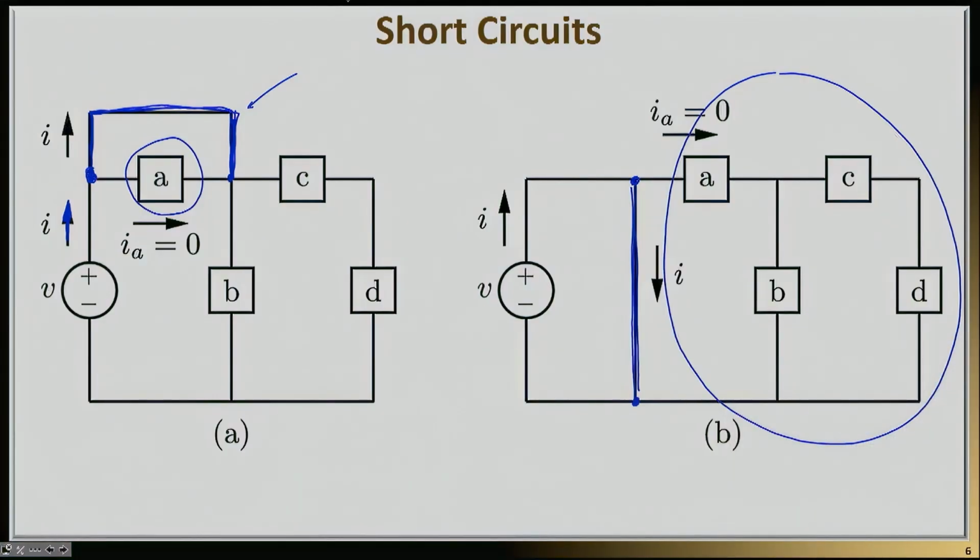Well, you have to be very, very careful because now you're basically forcing the current that flows from this independent voltage source to go through a path of zero resistance. We'll discuss resistance in more detail later on, but I'm sure that you all have an intuitive understanding of that. Essentially, that means that this current I could be simply too high.